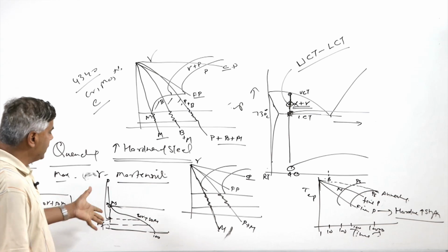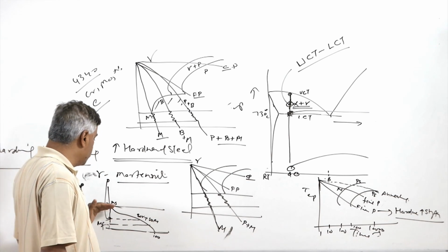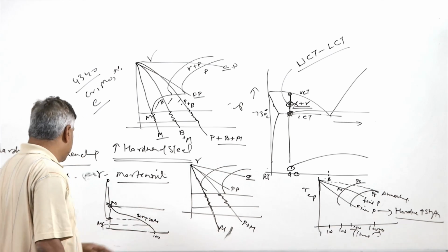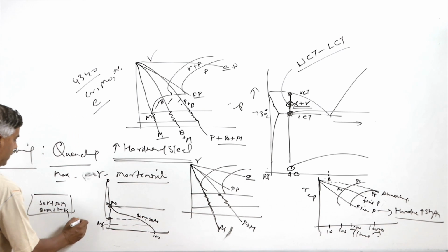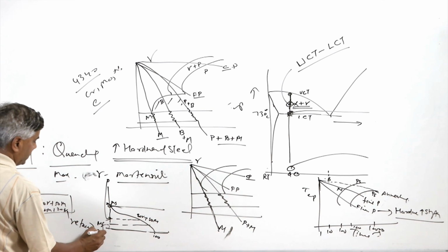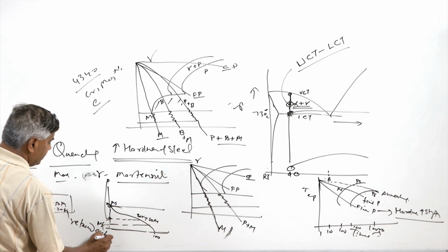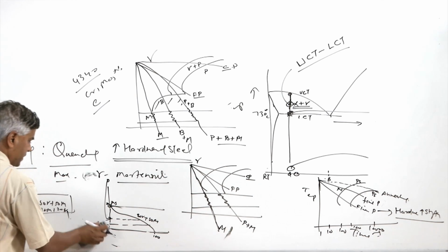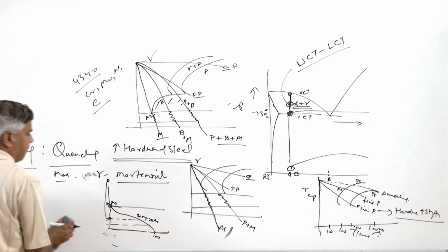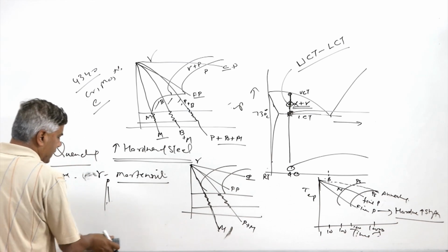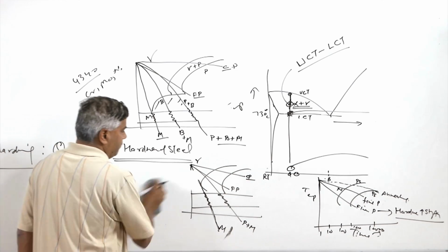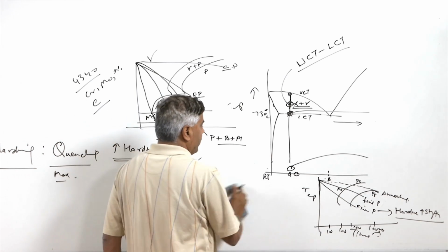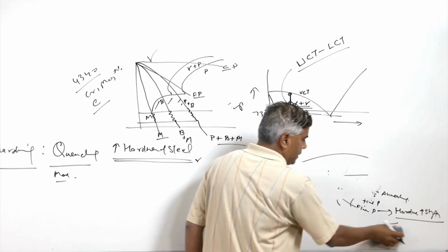Whatever austenite is left after the quenching to a temperature below the martensitic start transformation temperature will be there as retained austenite. This retained austenite basically reduces the hardness of the quenched steel. For hardening purpose, it is expected that the entire austenite will transform into the martensite. That's why the quenching is done at a temperature below the martensitic finish temperature line.